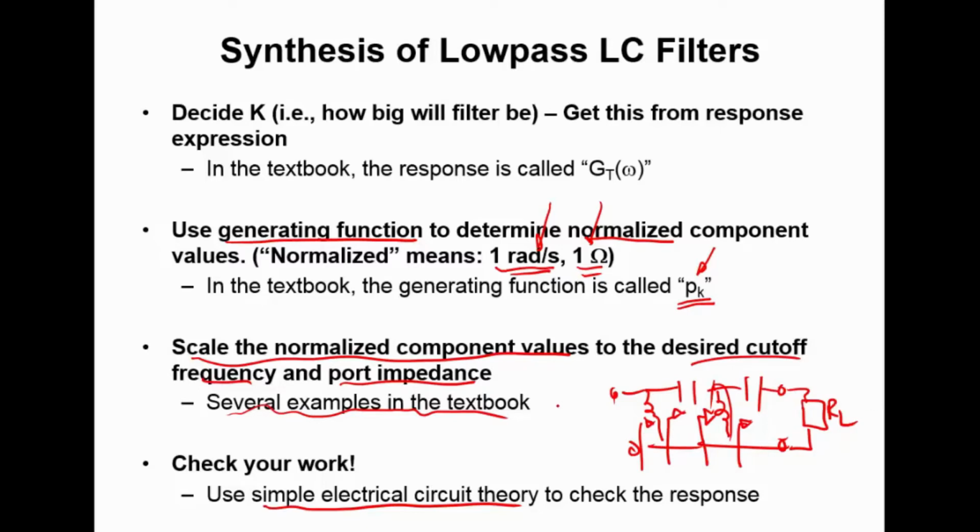And you know what the specified impedance is. So you can quickly work out, for example, the reflection coefficient. And from that you can get the transducer power gain. So this is a very, very simple calculation to do. The best way to do this is in MATLAB. You can do it in pen and paper, but it tends to be a lot of tedious number crunching. Instead, just set up a simple MATLAB program, which just walks you through this particular process of stage analysis. And then check and make sure you get the right transducer power gain.